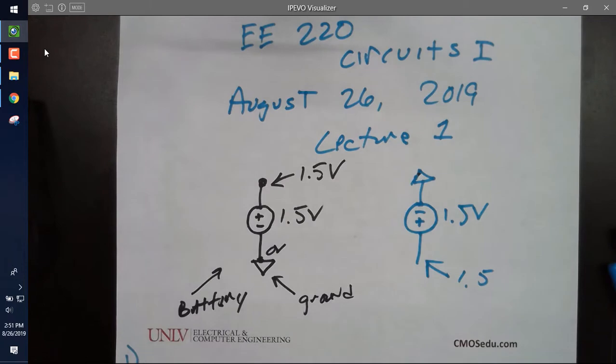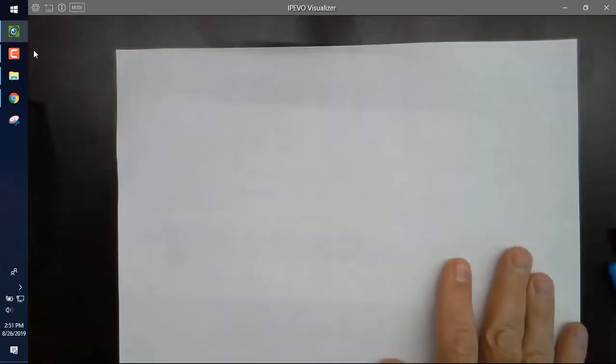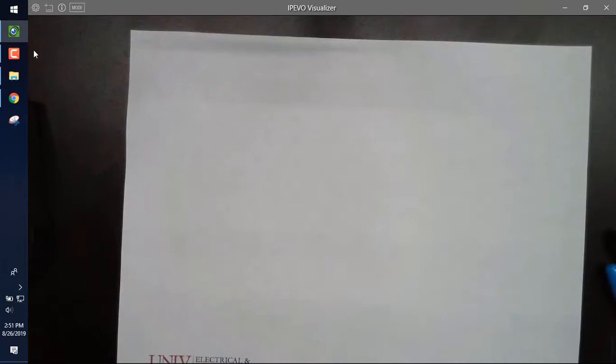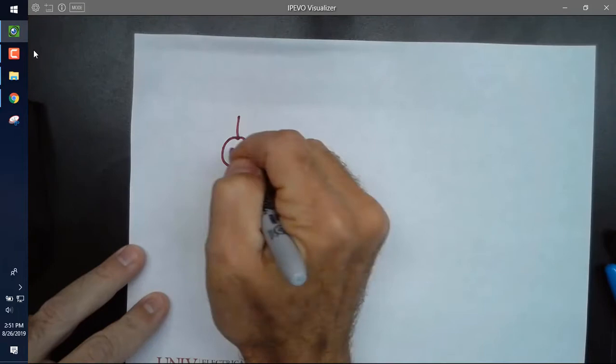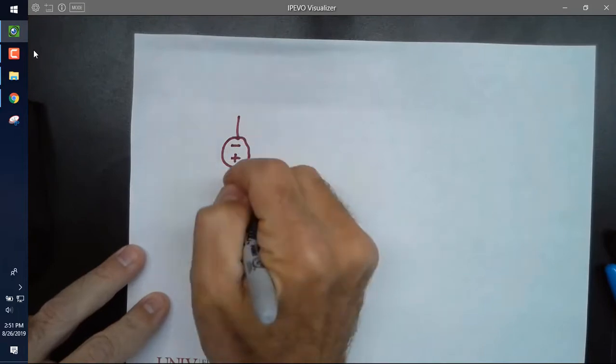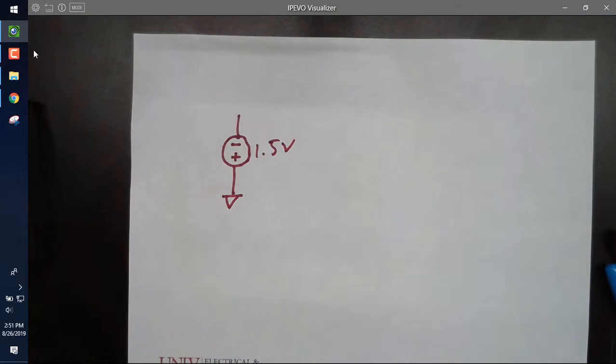Okay, all I'm going to do now, and this is something I had a problem with when I was learning, so I'm going to flip the battery around. Okay? And I'm going to say, okay, here, before I add it, the minus connected to ground. Now I'm going to do this. And I'm going to connect the plus to ground. So when I was learning, I'm like, wait, what? You can't ground the positive of the battery? That doesn't work. Well, yes, you can. In fact, a lot of diesel cars, they ground the positive and they use a negative battery.